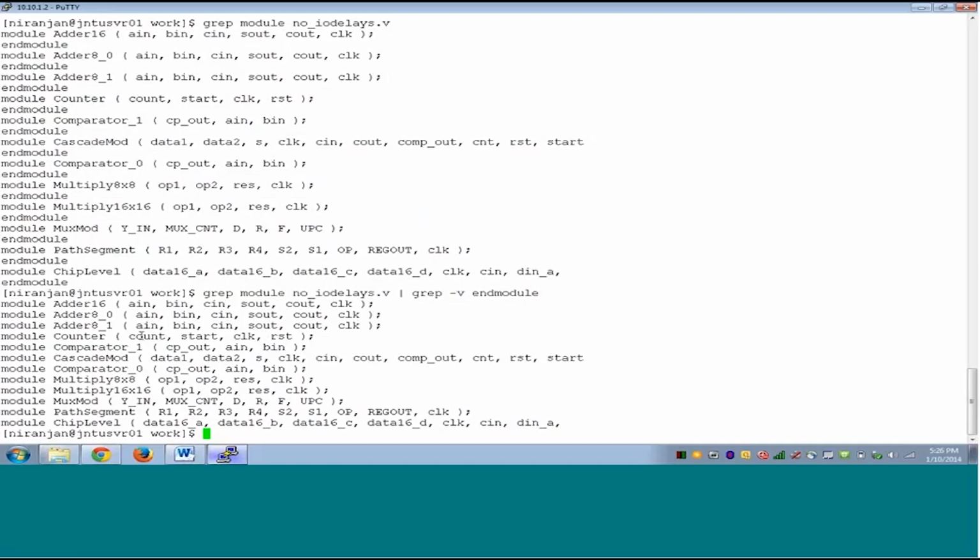Although in RTL the module name was same, when it comes to netlist, it will make independent copies. Now when the design is synthesized, adder 8_0 has nothing to do with adder 8_1. Although the functionality is same, the implementation might be entirely different because each of them will get optimized according to its own design goal.